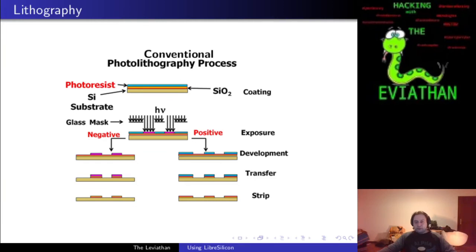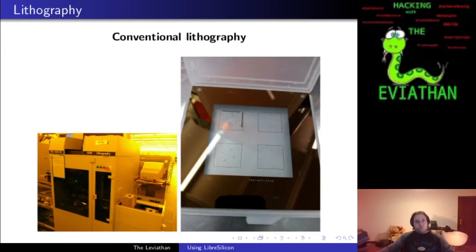Then this pattern is focused again and projected onto the photoresist, which chemically reacts in the areas where UV light hits the resist. And after development, your structures have been transferred onto the wafer. Typically in industrial setups, you use something like a big stepper unit, which takes cassettes full of wafers. As mentioned in the beginning, it batch loads those wafers.